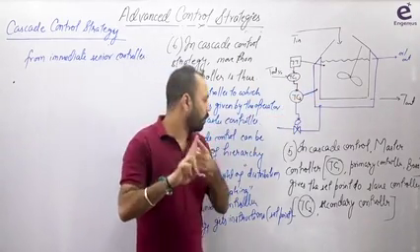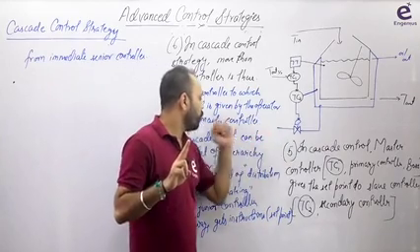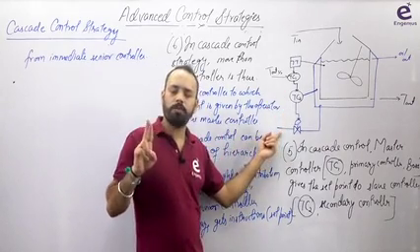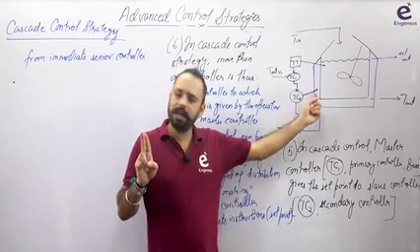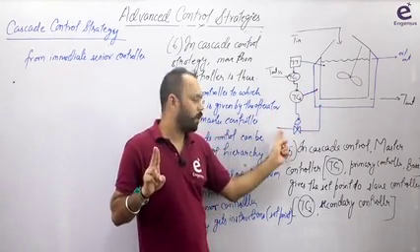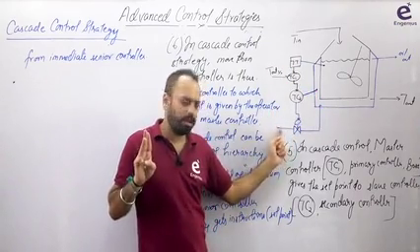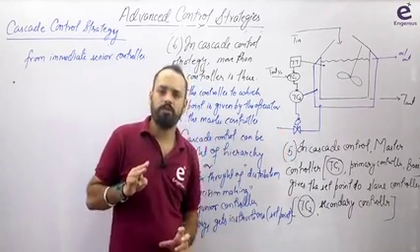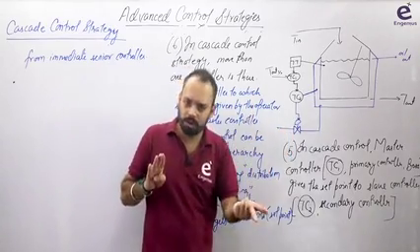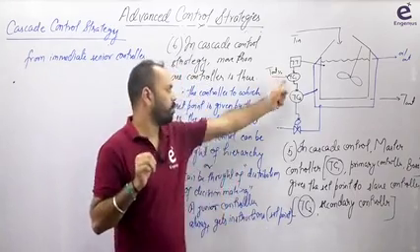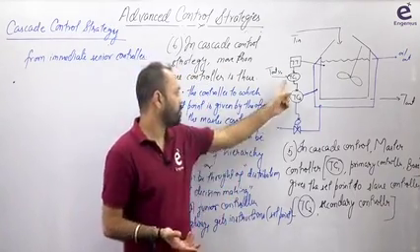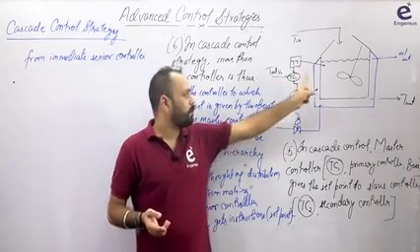Then it was deciding, second point, what should be the flow rate, what should be the oil flow rate to maintain this jacket temperature. Then it was deciding for maintaining this oil flow rate, what should be the valve opening. Then it was deciding for this much valve opening, what should be my output. 4 decisions taken by this controller, right? But right now, what decision is taken by this controller? That what should be the jacket temperature.